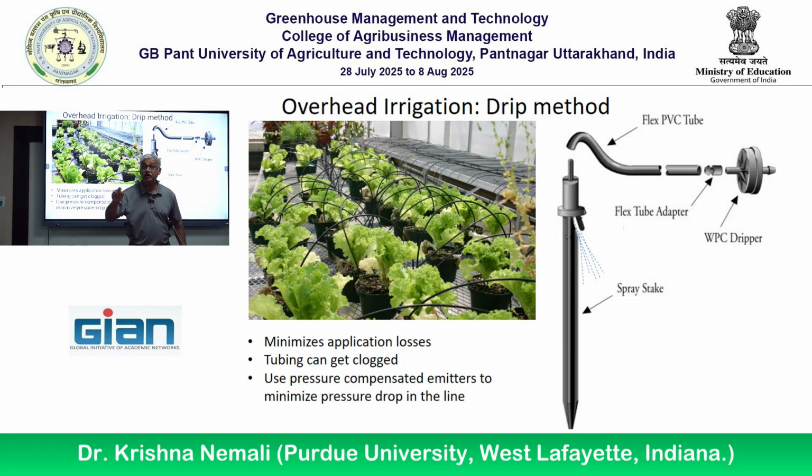But also there is one more thing I wanted to measure. How uniform is water volume in all these buckets? In that bucket I am getting 5 liters. In this bucket I am getting 1 liter. There I am getting 3 liters. Then you have a problem. You did not do your drip system well. What's going on? Where is the pressure falling apart? Wherever you are getting a lot of water, that is where there is a lot of pressure. Where you are getting less amount of water, the pressure is dropping. So you may want to do something.